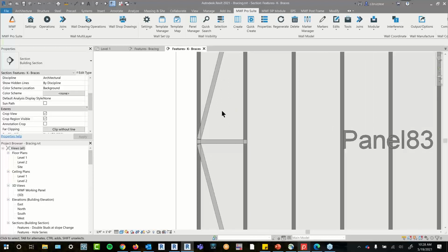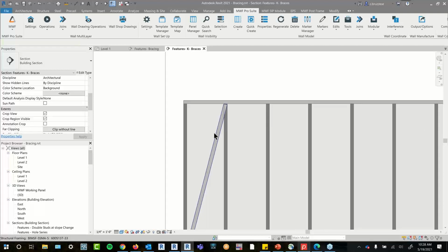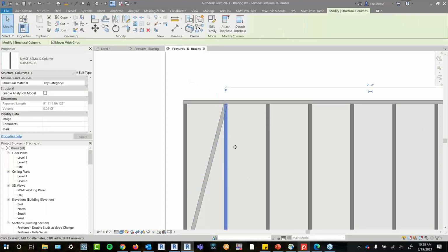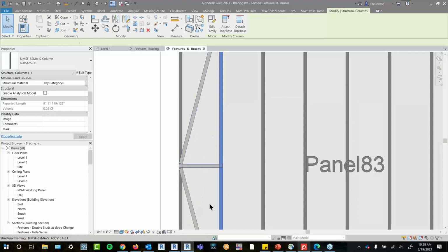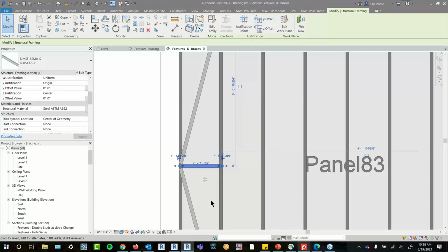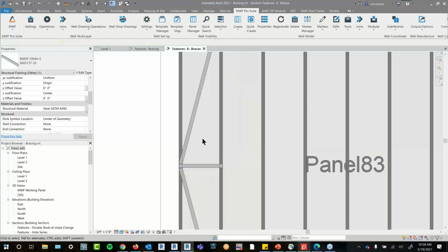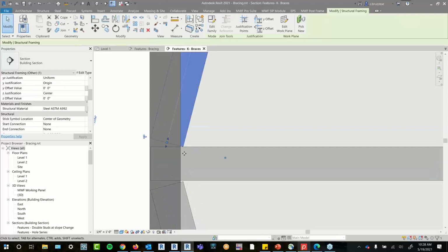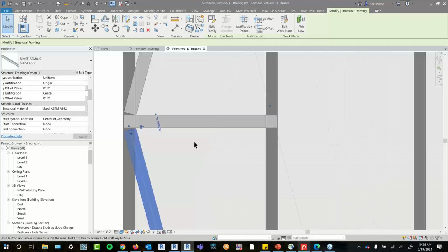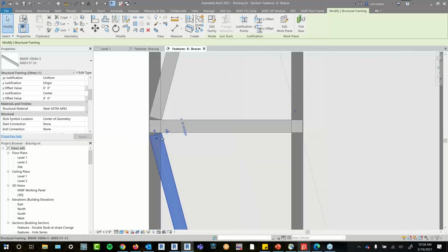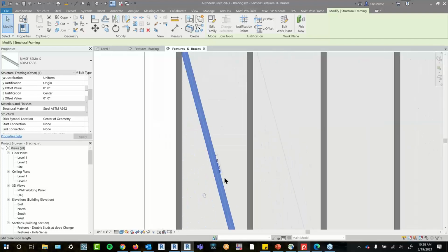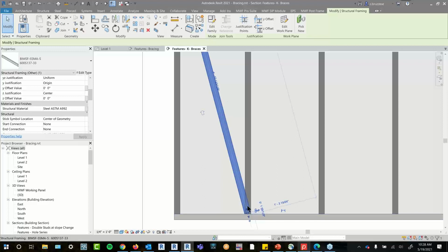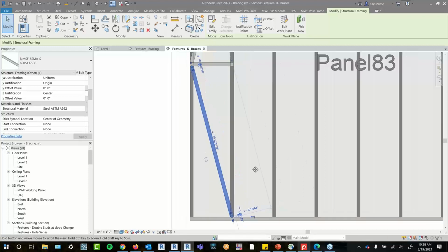So nothing too complex, really. Again, it's just actually in your structural layer, so it would lap onto your studs. And we do add the horizontal by default. So where you can start getting into some of the clearances is, this might be a little too close to your horizontal member. This guy as well. So I can maybe just add 2 inches of clearance, let's say from my horizontal blocker, and maybe also from my tracks. I want to raise this a little bit so I can add that bit of clearance.